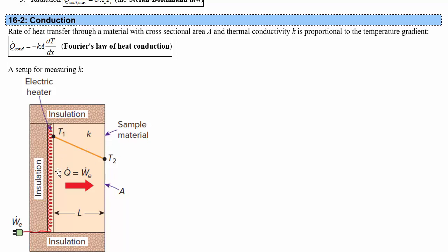Now, if the surface area is a constant, as in a setup like this, where you've got insulation here, insulation here, insulation here, the heat can't be flowing through those insulation areas. So all the heat must be going this way. We've got constant cross-sectional area. If we're looking at steady state, then the temperature isn't changing at any point, so the heat isn't building up at any point. So all the heat that flows through this first cross-sectional area has to be the same all the way along, because it also has to flow through these other cross-sectional areas and flow out the material. Same heat flow through all the different cross sections.